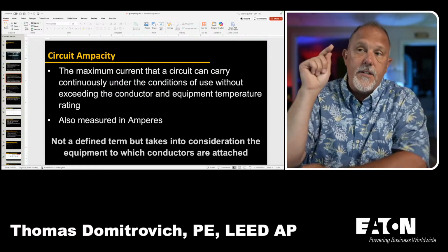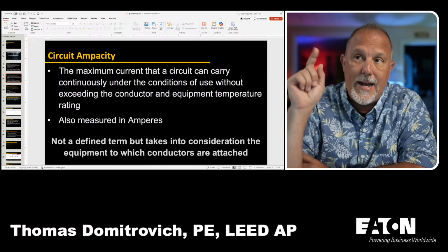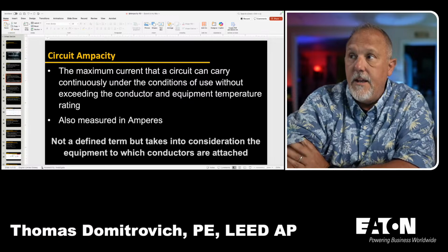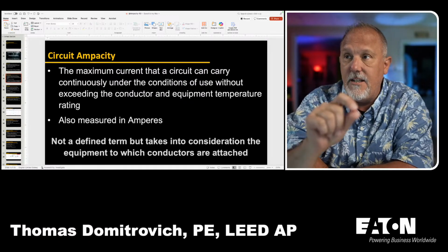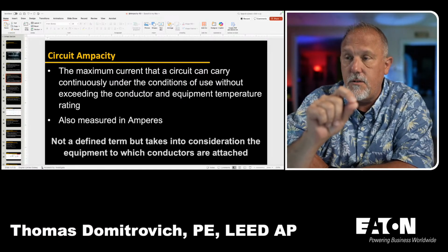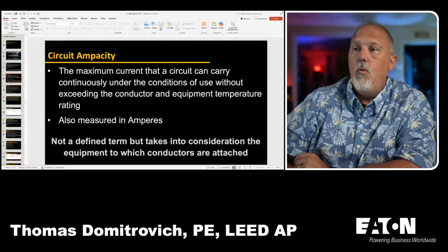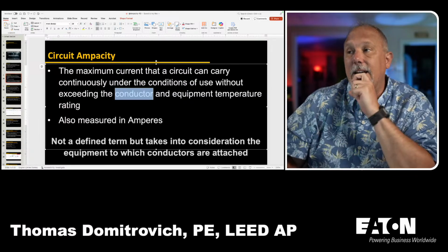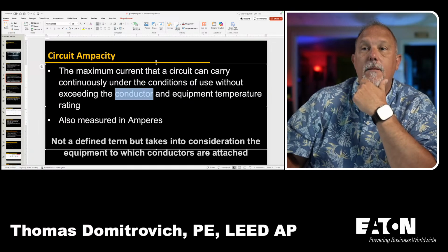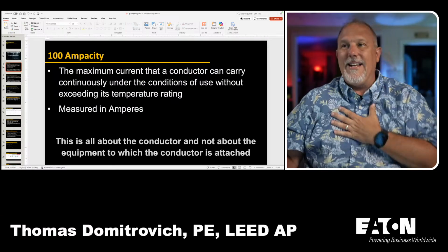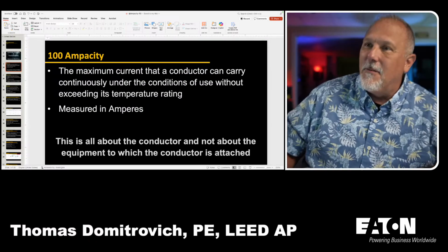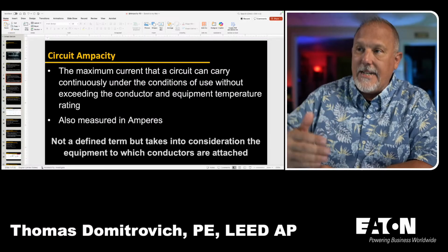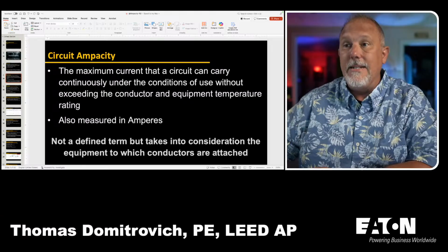There is no defined term circuit ampacity, but I'm suggesting that it's the maximum current that the circuit can carry continuously under the conditions of use, without exceeding the conductor and equipment temperature rating. So I added exceeding the conductor and equipment temperature rating.